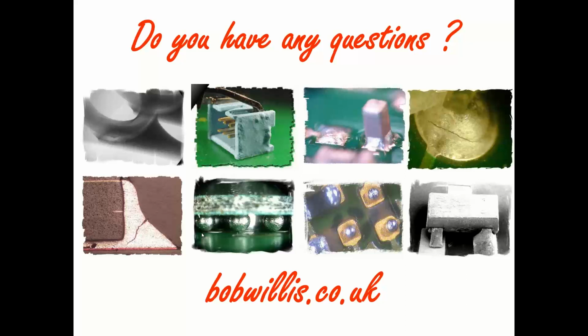The one thing about any rework of conformal coating is knowing the material, and making sure the material is going to soften at the soldering temperatures you're going to use, because you don't want to try and lift the part off and damage the board or damage the solder mask or pad areas. You want to be able to repair it in exactly the same way, whether conformal coating is there or not.